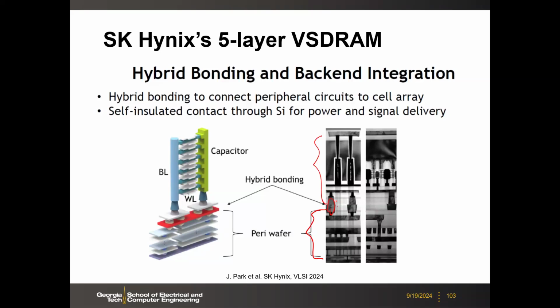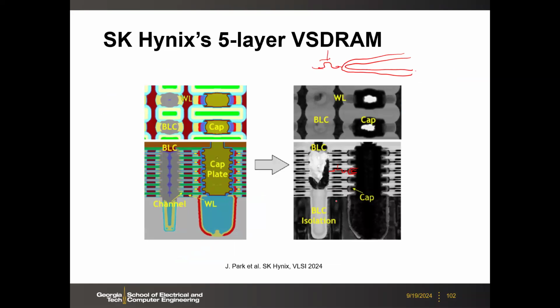So here, from my initial estimation, of course, we don't know how large the capacitance should be. This really depends on how good this transistor is in terms of leakage. But if you think about the conventional 2D DRAM, this aspect ratio is approaching 100, right? So this is like 100. That means this is very long.